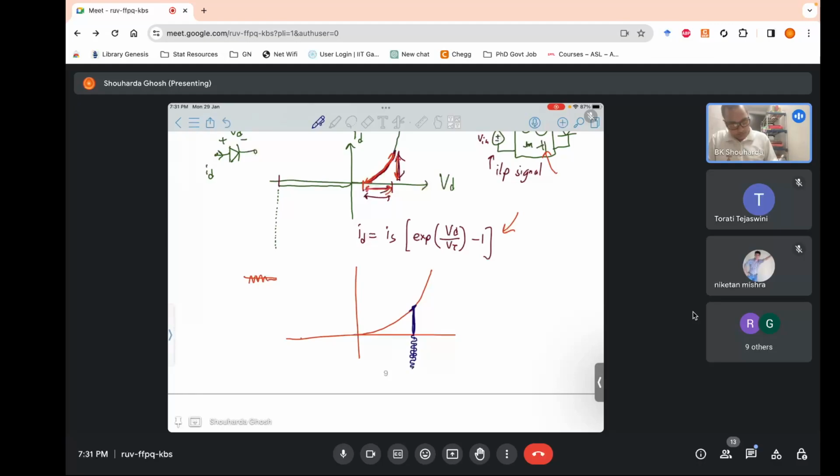So if I zoom in on this point, let's say it has a fixed voltage, V0, our signal V in is around a fixed DC and it is fluctuating with a small value. Let's say my signal variation is delta. So this goes over delta by 2, this goes over delta by 2, and your output will actually vary along this.